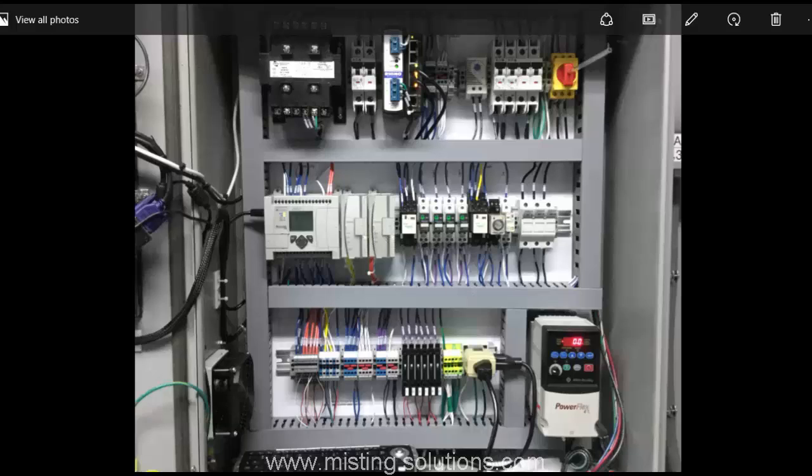Those analog signal inputs come from the pressure transducers, water pressure on the output and input side, and the water flow meter, and then also the temperature sensor that is down monitoring the bypass water temperature. And this middle one here again has two outputs, and the output that actually drives the variable frequency drive gives it a 0 to 10 volt DC signal to tell the motor what speed it should run at.